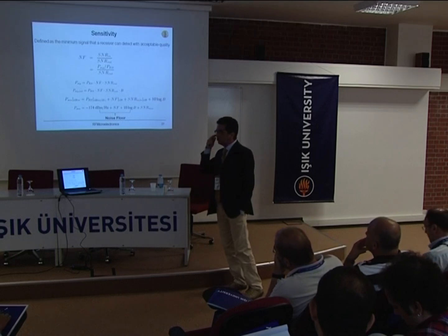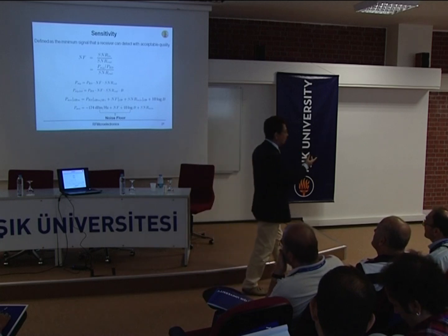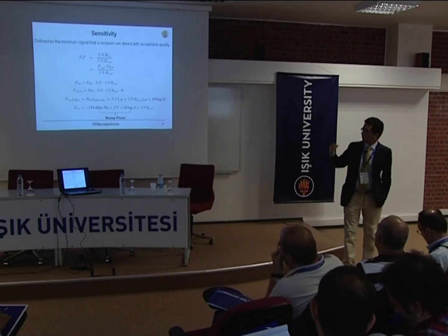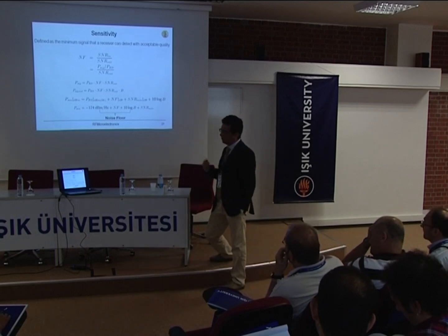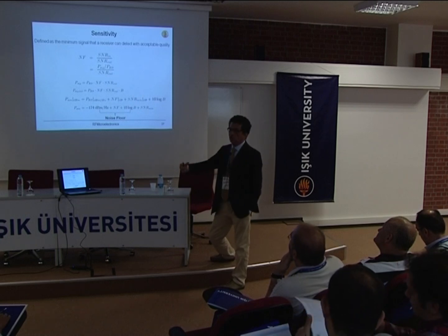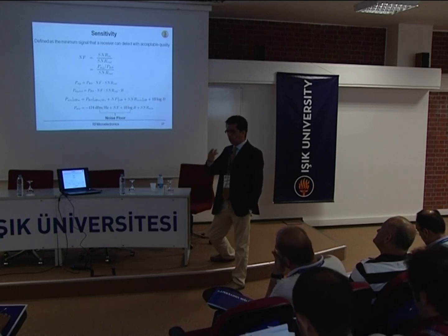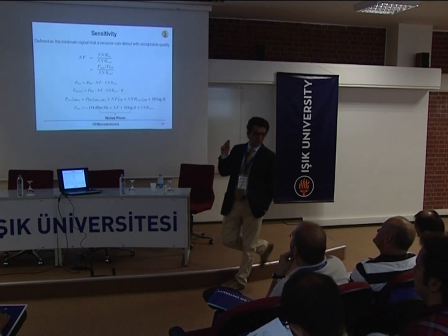For example, in a typical QPSK for wideband CDMA, which uses, again, an alternative version of QPSK, the signal-to-noise ratio, when we enter into the digital processor, also called Eb over N0, is 7 dB, just to have an idea.